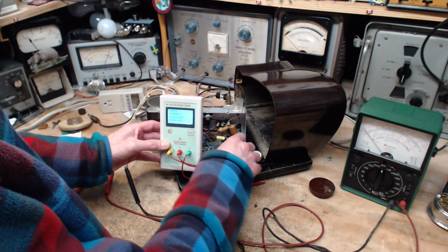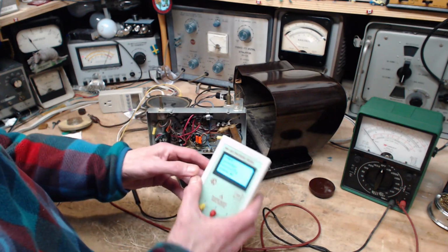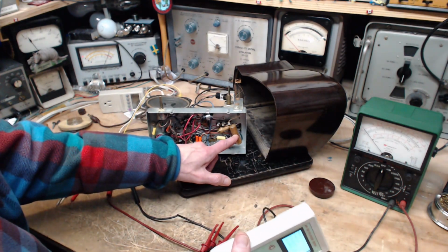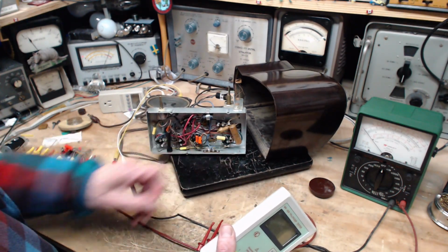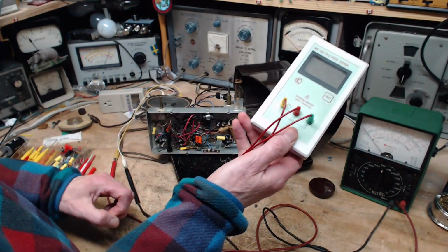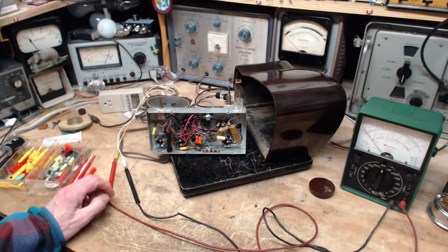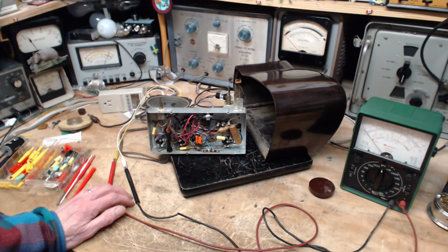So I think what's going on is the instrument here can't read certainly a capacitor of this sort because it has this coil thing happening in it. But any capacitor that's leaky will start giving you false readings on you. You get higher and higher readings of capacitance. And that's probably true of every capacitor tester. Okay, so that didn't do any good at all.